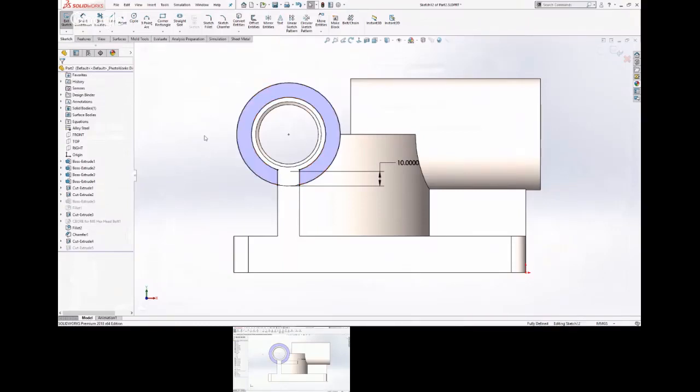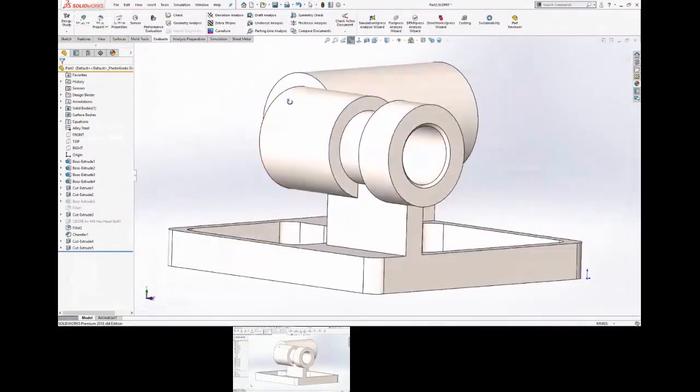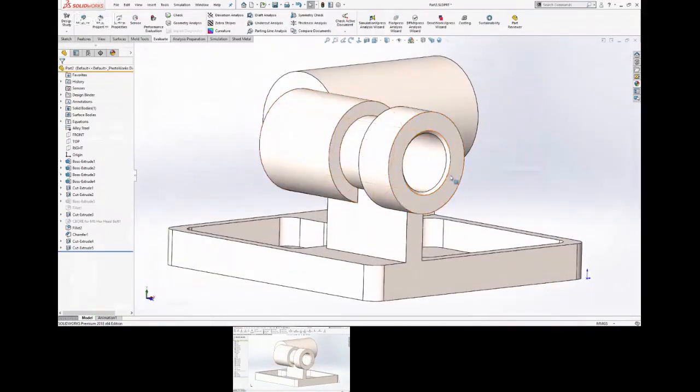Earlier, when you were able to highlight the entire circle all the way through. Oh, convert entities. Are you doing the convert entities tool? You just selected that face and that was it, right? Yeah. So when I go into a sketch, you'll see I tend to click things in certain ways if I know I'm going to convert entities.